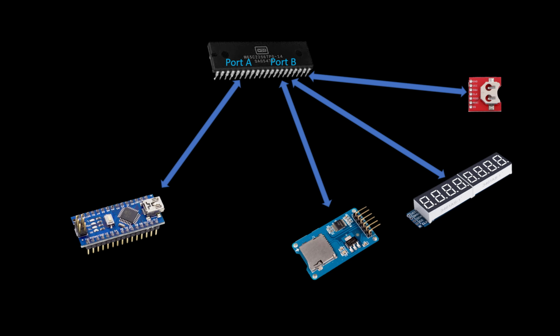And in the last video I thought what I would do is connect it to port B. And I did start that way, and I ran into an issue. And that issue was that my SD card reader is always pulling the MISO line high, even when it is not selected. So even when chip select is high for that SD card reader, I, for some reason, am seeing it pull MISO high. And now remember, MISO is data coming from the slave device back to the master, which in this case would be port B of that VIA.